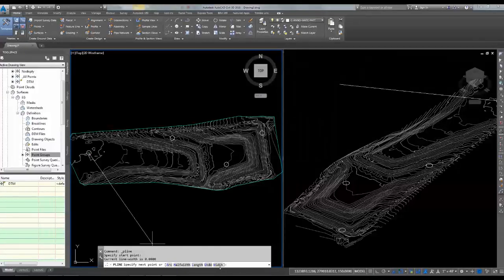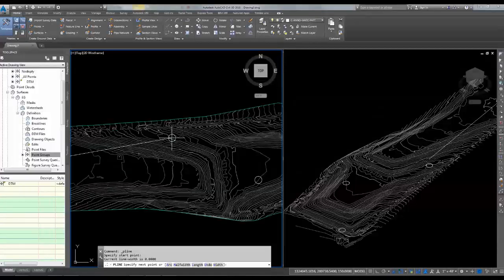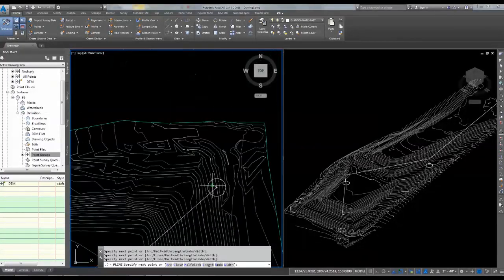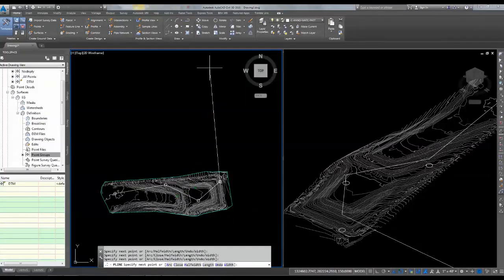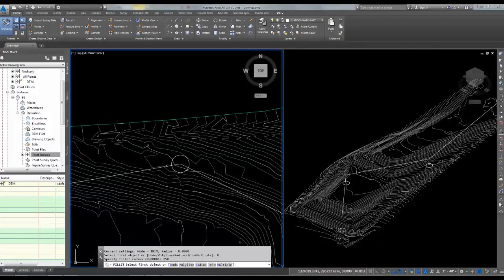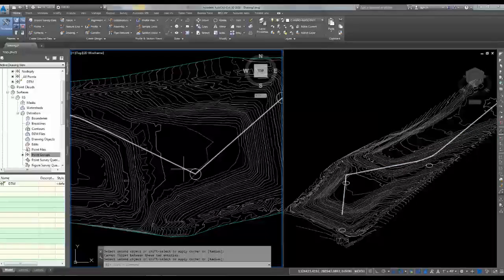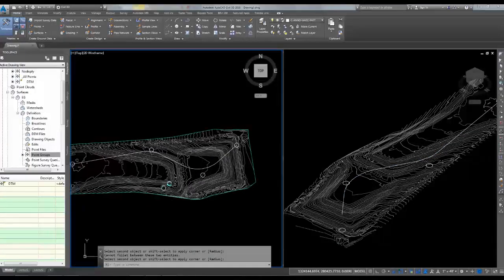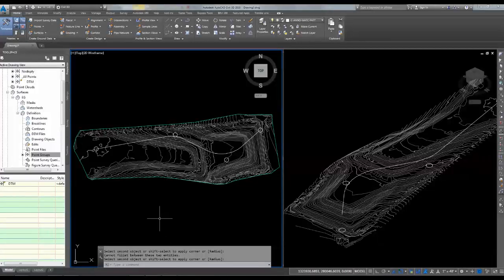I can put in the arc and half width and all that, but I'm just going to do it the way I think most people would: they would drop in these points at the center of the circles. Then they would use the fillet command, set the radius to 250, and then pick the lines. So I come in here and grab those, repeat the command, and pick that one and that one. So we've got that.